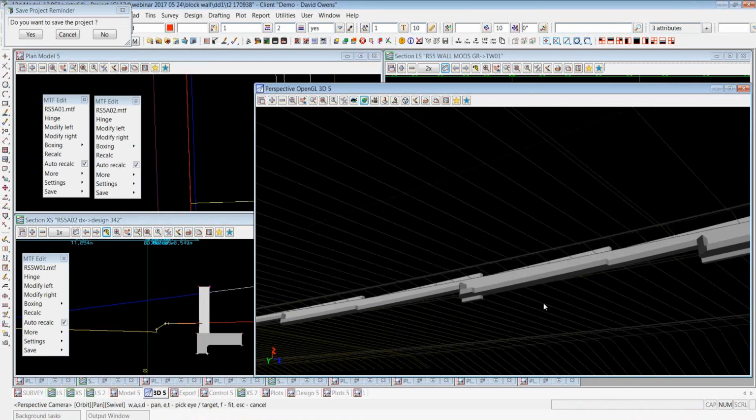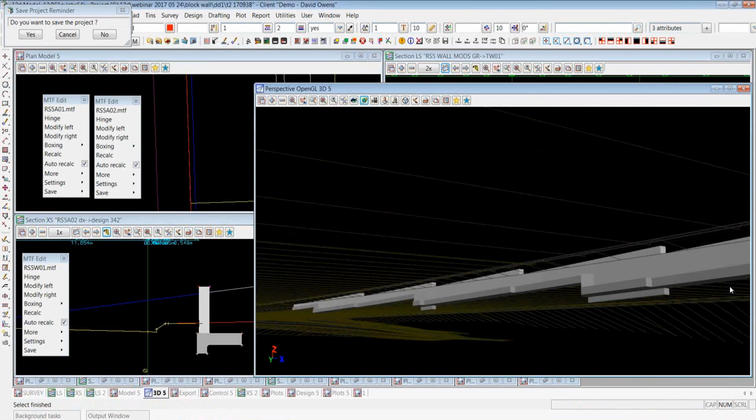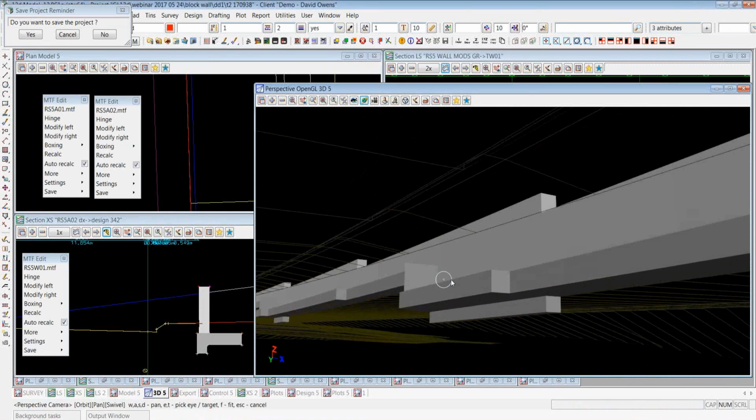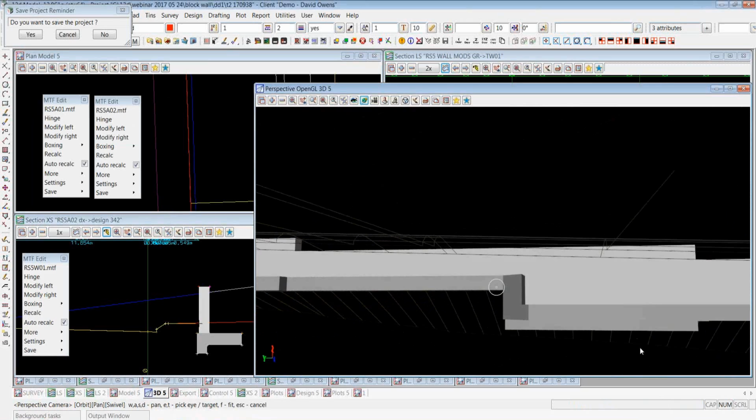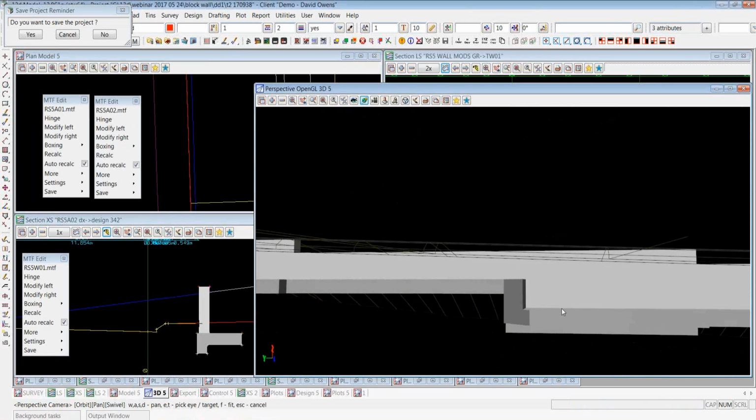Yeah. One other thing which was a little bit tricky with this one was getting the overlap. Because where the wall itself steps up, the footing needs to project through just that little bit further so that we've got something to tie the two different levels of slab together for the footings. And that was a simple little modifier which I've built into a snippet.